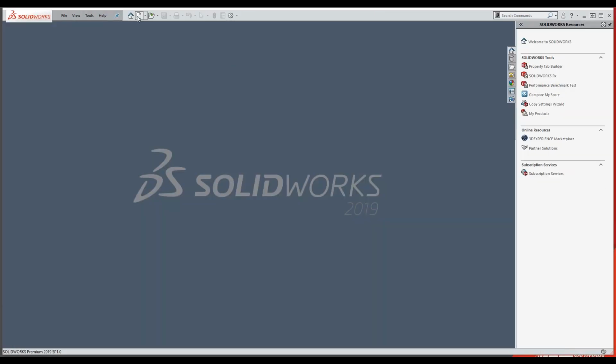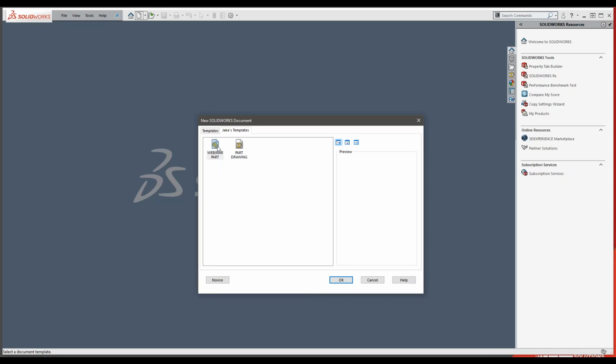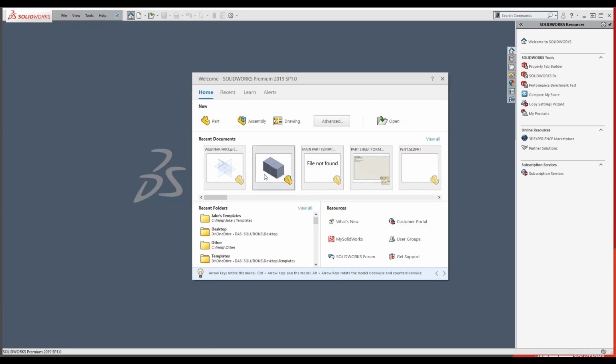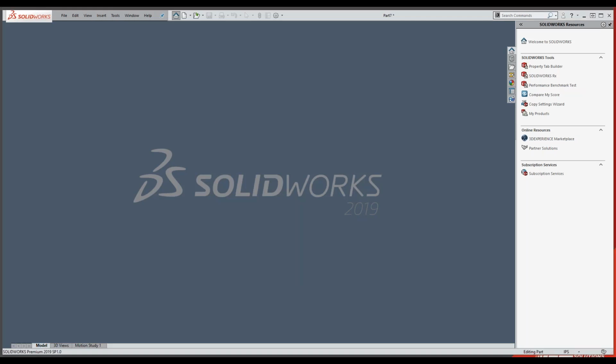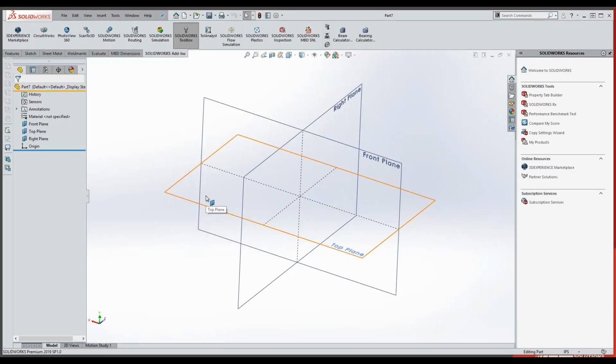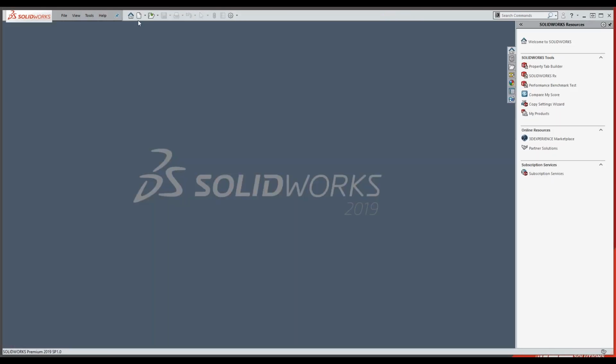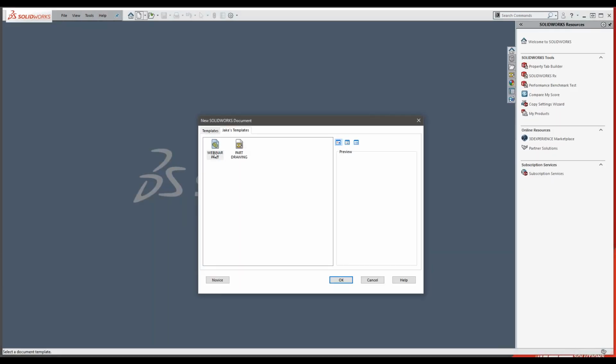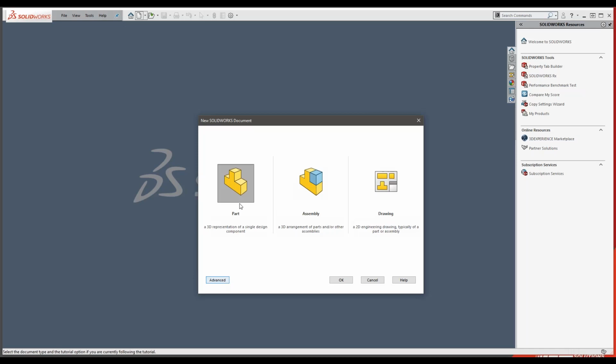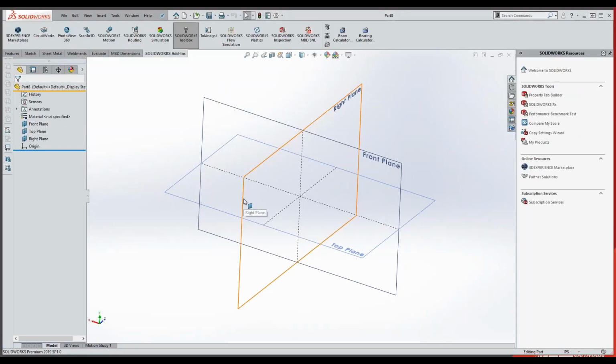so that now if I say a new part, it goes right to that one instead. And if I double click to create a new part, it goes right to my template instead of that default one that was there. By the way, under this, if I switch this over to novice and just select a part, that will also take me to that default location that we just placed in there.